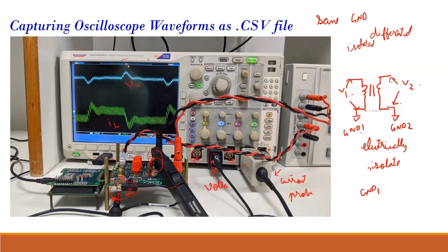This is the entire probe; it has certain connections, one goes to your signal and one goes to your ground. I think the outside is the ground, so you should know which is the ground part and connect it accordingly. So you can check that on the multimeter.